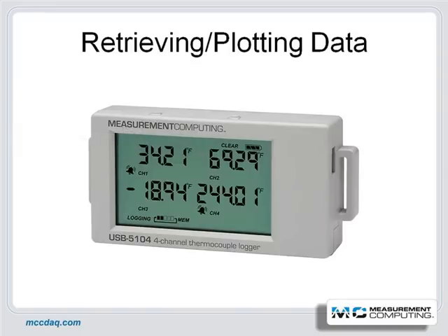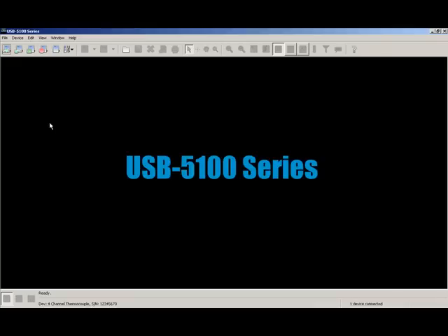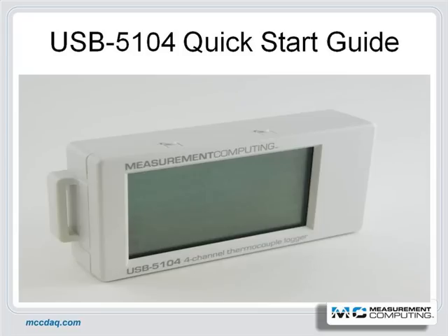When your testing is complete, you will need to retrieve your data. You can do this using our USB-5100 software package. The logger will continue to log data unless you have stopped it or it is full. You can stop the logging session by depressing the same button used to start the logger. Connect the USB cable to the USB-5104 and to your USB port.